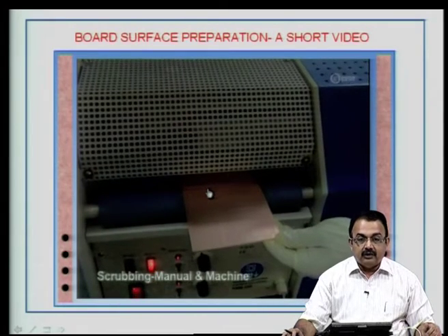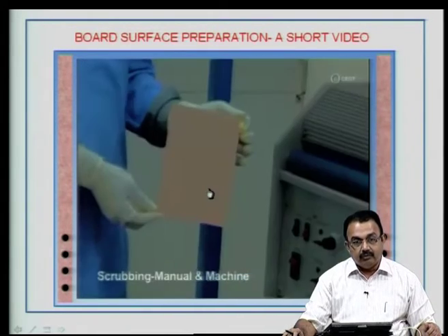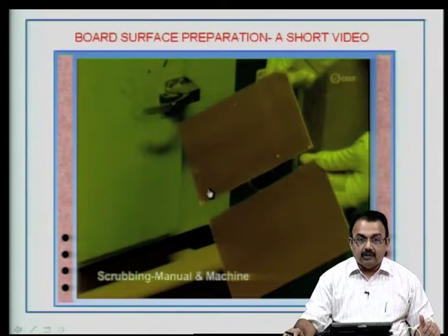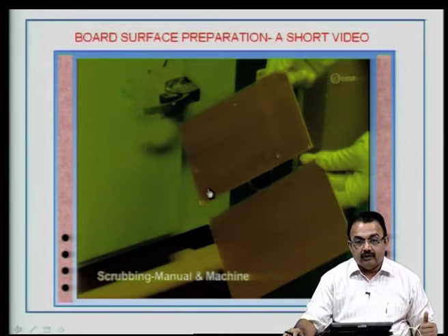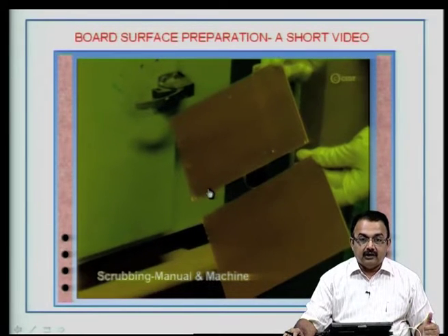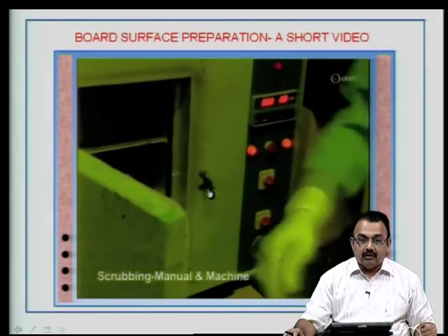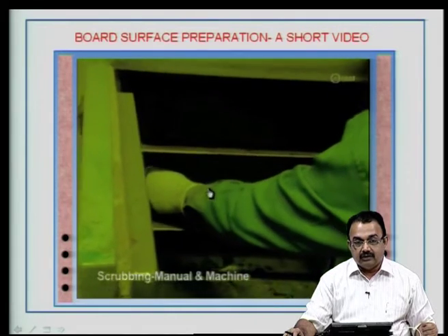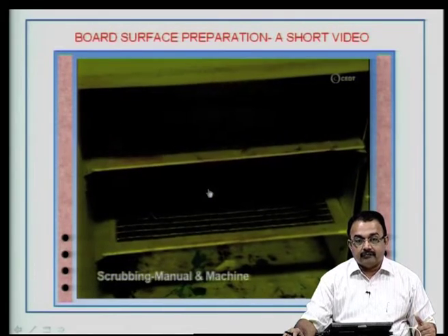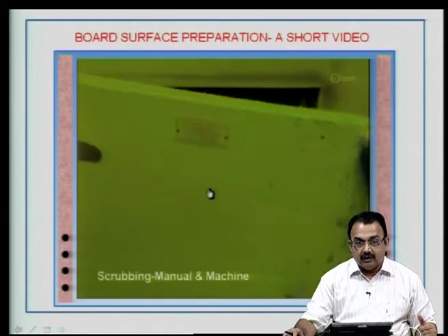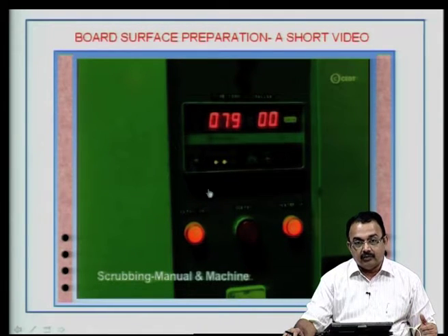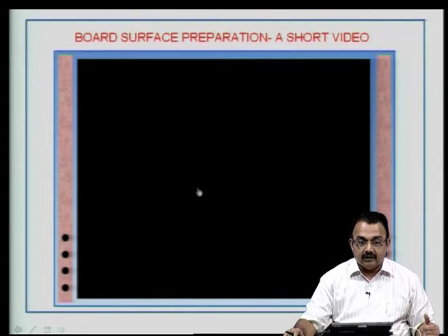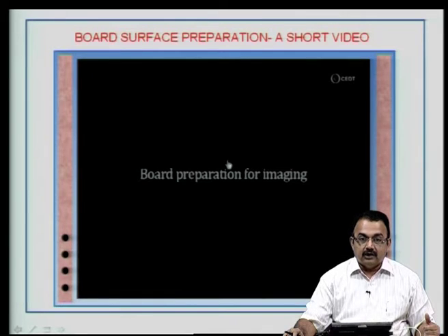Sometimes you can use a jet slurry containing pumice. Okay. You can use water mixed with the pumice material, and then you can form a slurry, and this slurry can be sprayed from the top and bottom of the brushing machine. Then you have the abrasive rollers. Together it forms a very nice methodology for scrubbing and removing your copper clad laminate, providing a larger surface area, removing the oxides and so on.